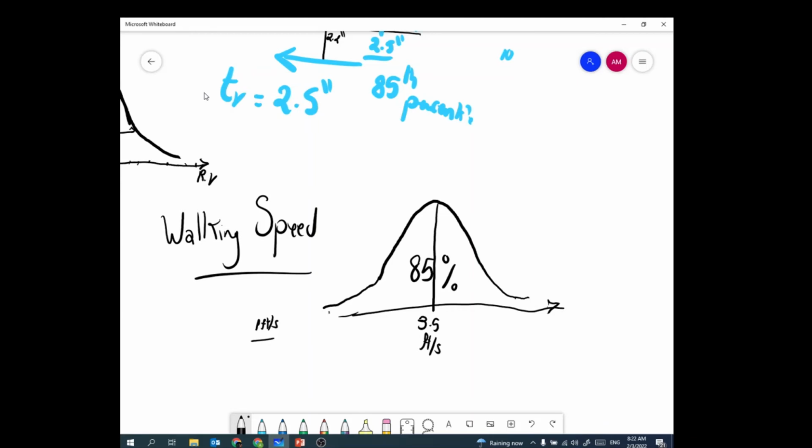So I say, yeah, I'm going to pick a value here, let's say 2 feet per second, or 2.5 feet per second. Again, it depends on my data. And the area from here up to infinity is taken care of now. So if a person is so fast, he's taken care of when he crosses the road. A person who is slower, well, again, enforcement comes here.